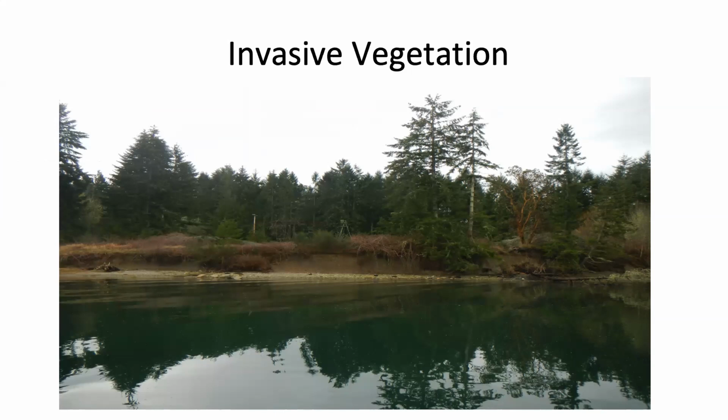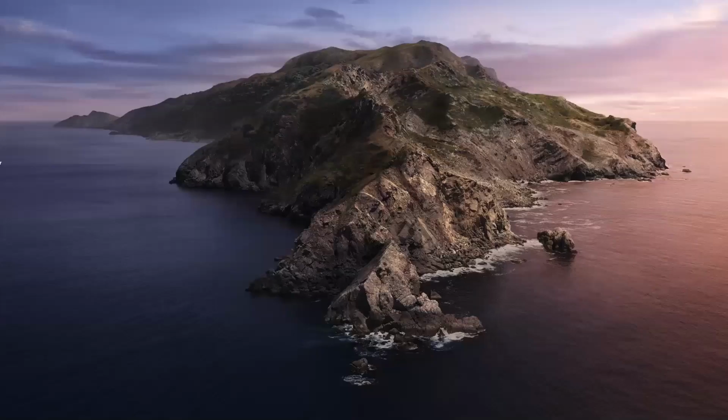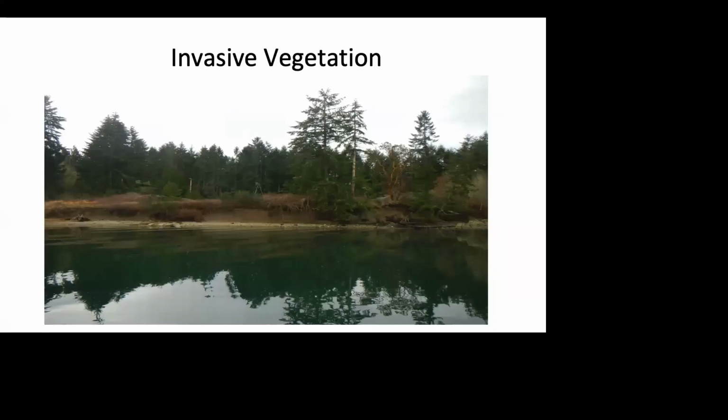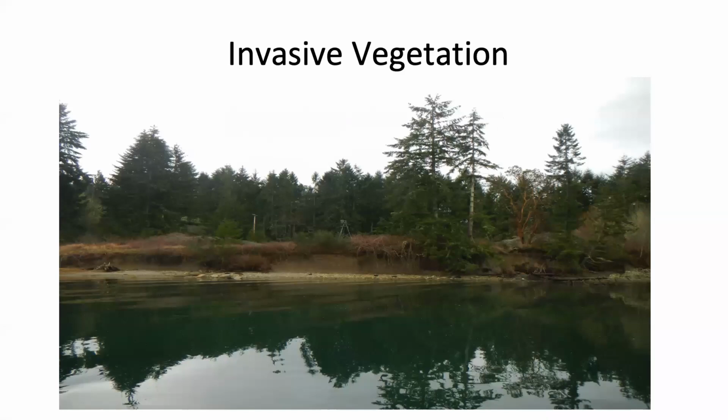They tend to be so successful because they grow aggressively. They have really shallow roots that spread really quickly and intercept rainwater, but do very little to hold a slope in place, especially at those deeper failure planes where deeper rooted plants can work. So I'm going to keep going. They'll actually crowd out the naturally deep-rooted plants, particularly on a newly cleared slope.